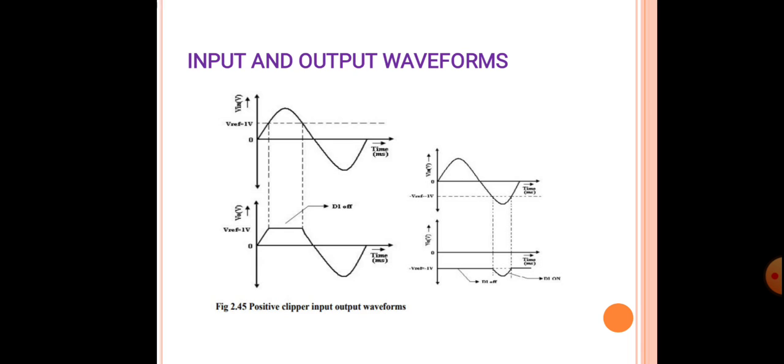And again, see on the right side we have input and output. Here the only difference is the reference voltage is minus 1 volt. So here the major portion that is above is clipped off and the portion below remains the same.